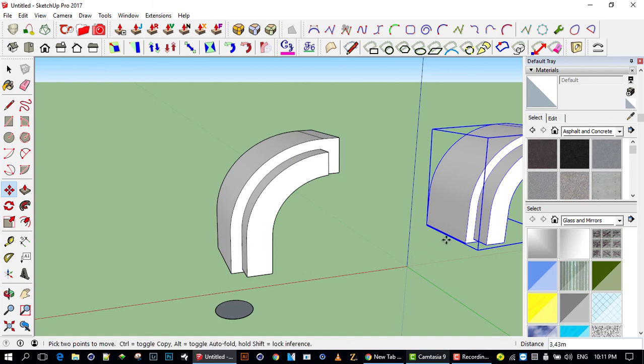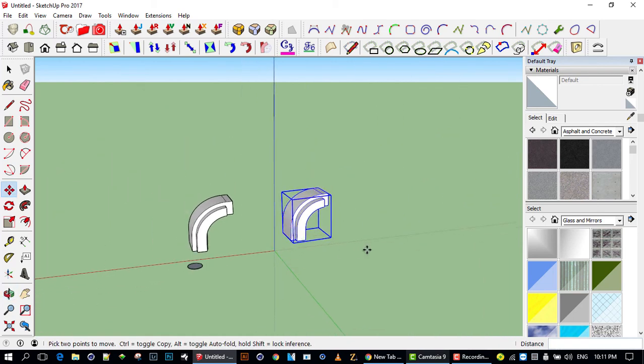And like I said before, if I do that and I want to create more copies, before I click off it, I can go to the multiply sign here at the bottom, which says distance in the right corner. It says ×2 and Enter. And if I decide now to make more, I can just go ×4, as long as I don't click on the screen. If I click on the screen, it then sets off there. So that's how you're able to do that.